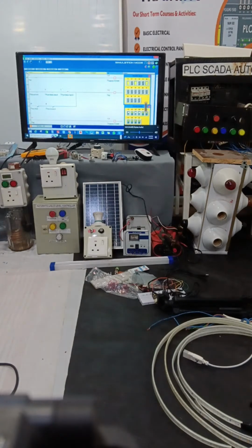Now coming to the 3rd stage, I am closing this. The contactor closes the 20 kVA capacitor, so the 3rd capacitor is on. Now coming to the fourth stage, this is the one equal to K4 and K1. So now all the capacitors are on in manual mode.